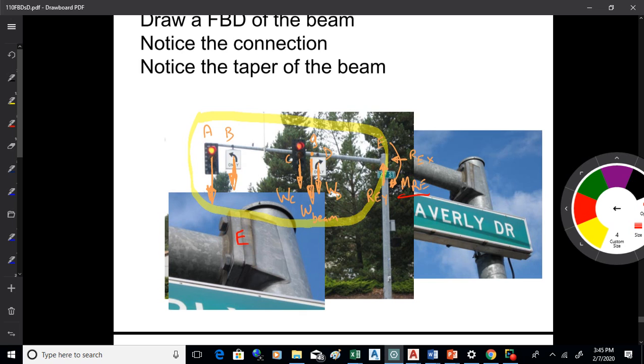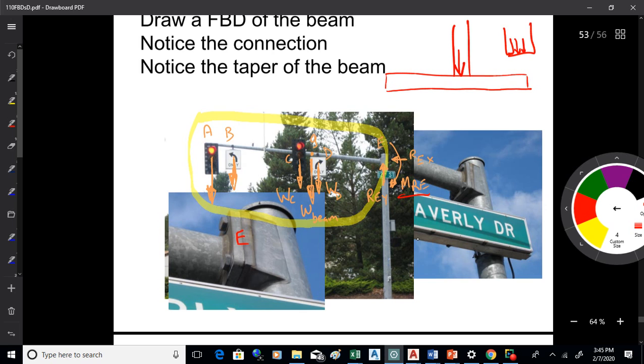Another situation you run into is if you have a beam and you're supporting columns, we model the columns as a point load, but columns aren't points. They have width. They're really a little distributed load. But it depends on what you're analyzing. If I'm analyzing the whole beam, I probably don't need to make a distributed load on every column. It's very similar to the question you just asked. So the way you analyze it just depends on what you're trying to figure out, okay?